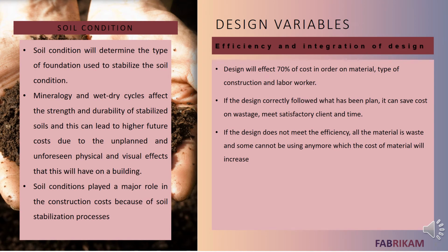Next design variable is soil condition. Soil condition is a very important thing that must be considered at the early stage before the construction process, because soil condition will determine the type of foundation used to stabilize the soil.